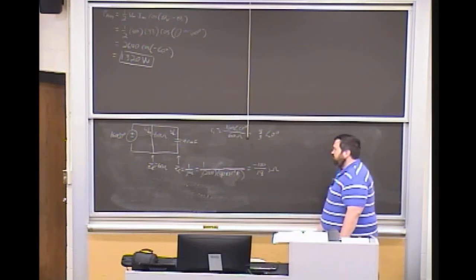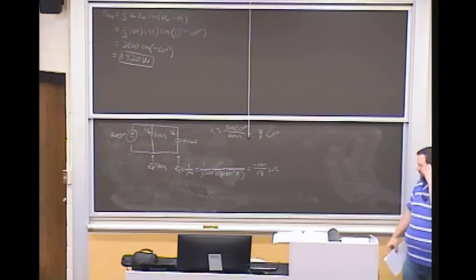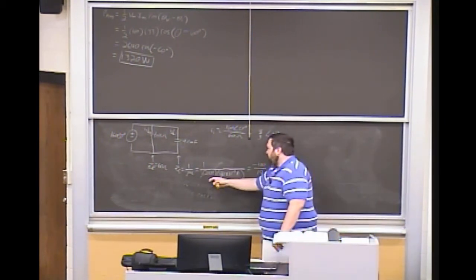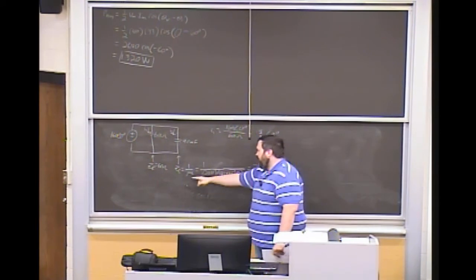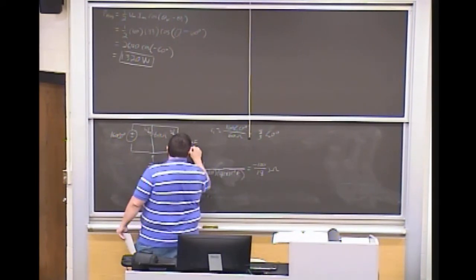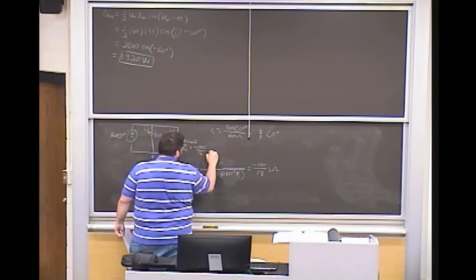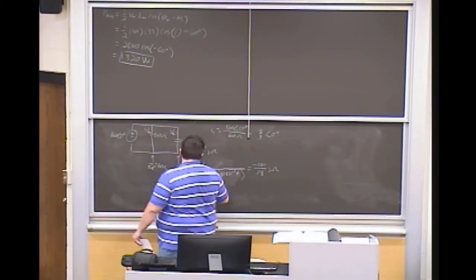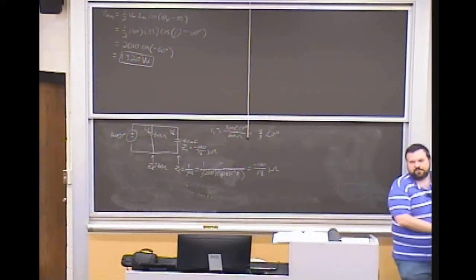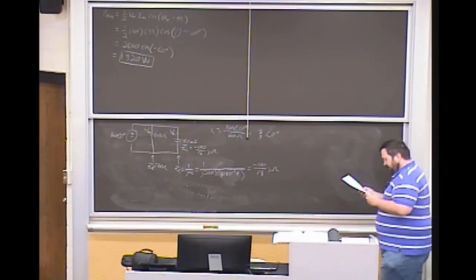Once you multiply all that out and take care of the fact that you have a 10 to the negative 6 down there, and you balance that out with this, the impedance of just your capacitor works out to be negative 100 over 18 J ohms. Because I did the whole multiply by J over J, becomes a negative 1 in the top, gets the J out of the denominator. That's what that works out to be.